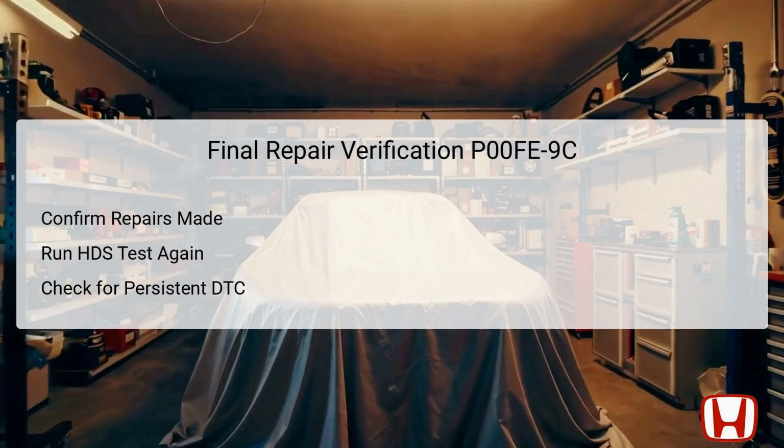After the completion of repairs, it is essential to verify that all necessary fixes have been successful. Run a final test using the Honda Diagnostic System, HDS, to ensure that the EVAP leak check module operates correctly. Check for the persistence of the DTC code P00FE-9C or any other related codes.